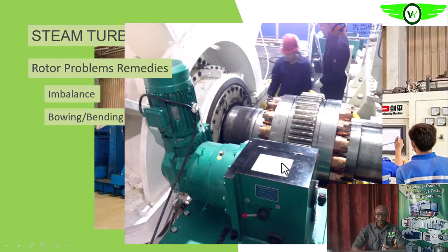This turning gear will be set into operation depending on the kind of turbine, the manufacturer recommendation and even our own operating procedures. The turning gear can rotate the shaft or the rotor of the steam turbine at between 3 to say about 30 rpm, revolutions per minute. So it actually depends on the recommendation of the manufacturer. So to help us do that is the turning gear.